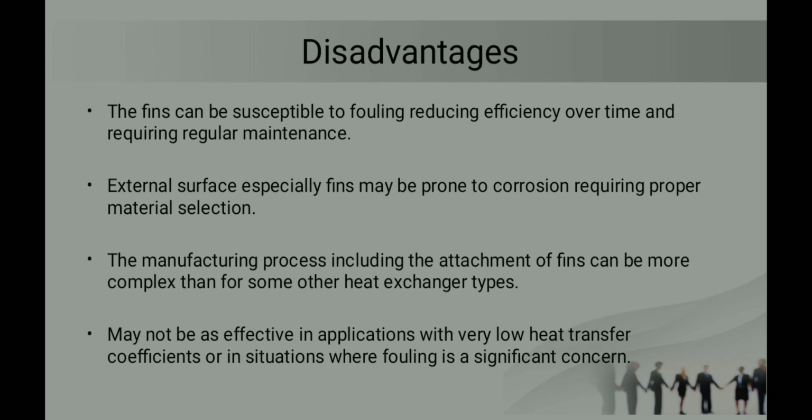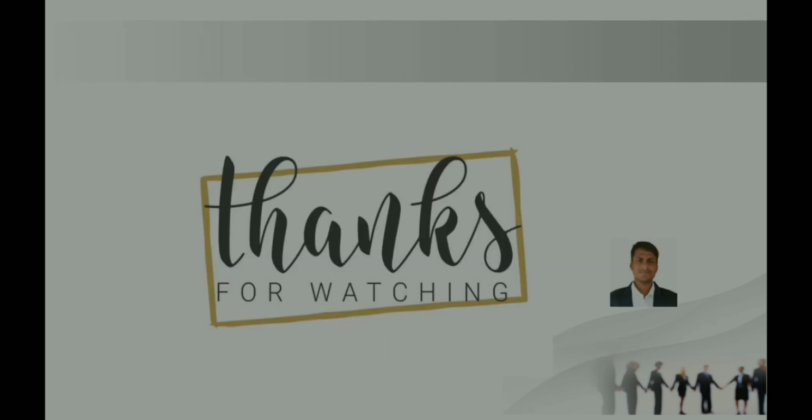And the final summary: a fin tube heat exchanger offers enhanced heat transfer efficiency, making it suitable for a wide range of applications in air conditioning, refrigeration, heating, and industrial processes. However, considerations such as fouling potential and material compatibility should be addressed in the design and maintenance to ensure optimal performance over time. The choice of heat exchanger type should be aligned with the specific application requirements and operational conditions. And that's all about a fin tube heat exchanger.